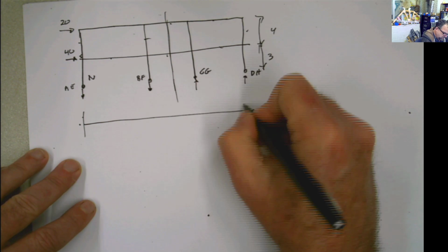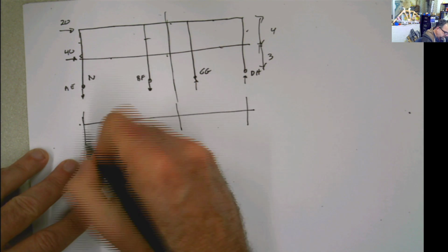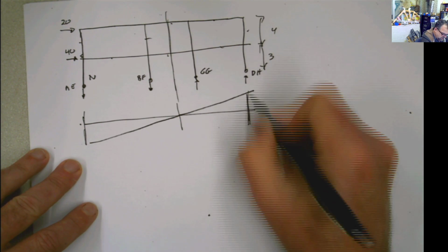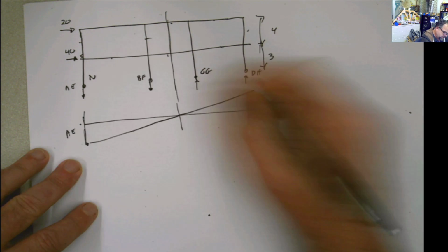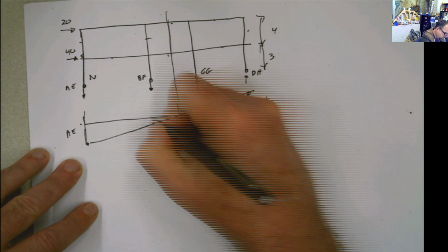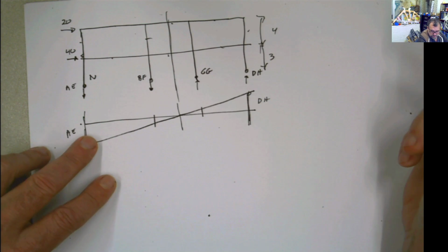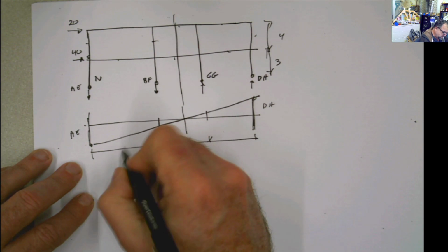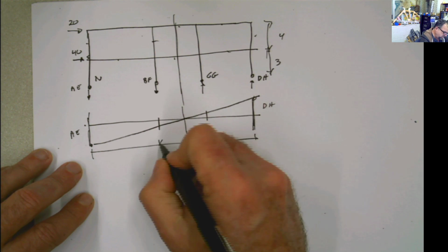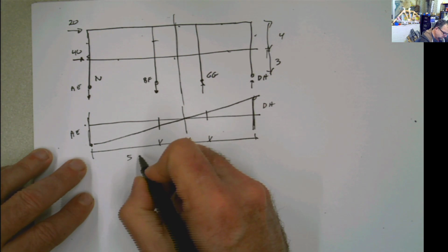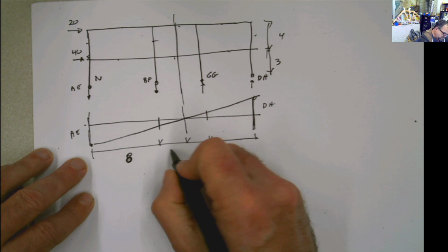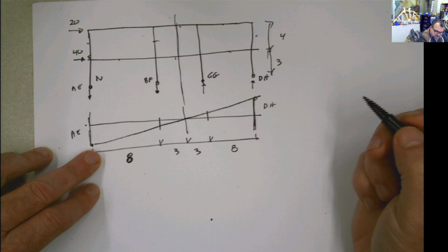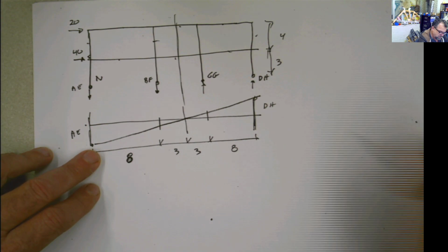And when you do the distribution also, then you're gonna have a similar thing that we got before. This is like that, pass it through the centroid, and to this value. This is AE, this is DH, and these two are the same. I mean, the drawing should be better, but you know, everything is symmetric. And because everything is symmetric, we are basically repeating what we did before. This is 5, this is 8, 8, this is 3, this is 3, and this is 8. And if you do the ratios between these, you're going to get exactly the same ratios that we got before.